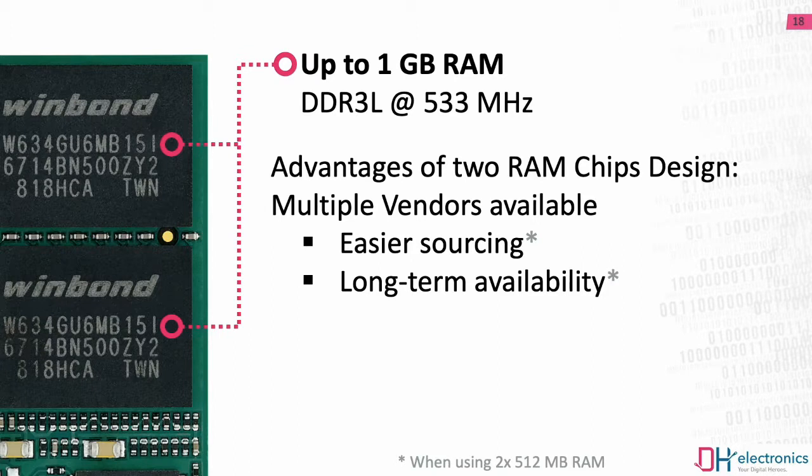However, DDR3L memory with only 512 MB of size is a standard component which is available by many vendors out there. And therefore, it is not only easier to source these parts, but also it ensures that we can provide all of our variants for at least 10 years to the market. Even if in a few years some vendor decides to discontinue this chip, it is still very likely that there are other vendors out there which are still producing this part, and thus we can make sure that we can provide all of our variants for at least 10 years to you as our customers.